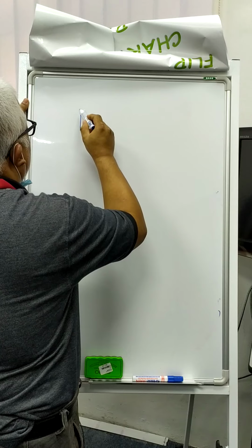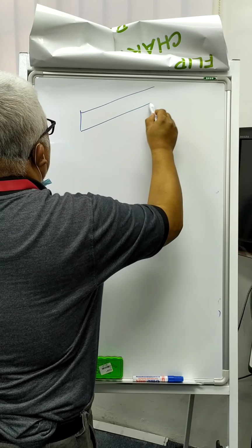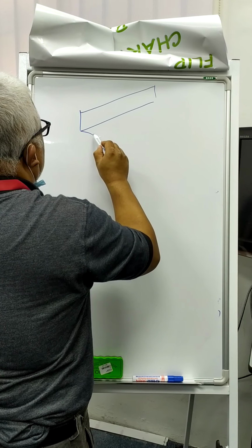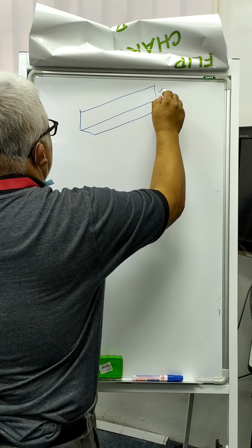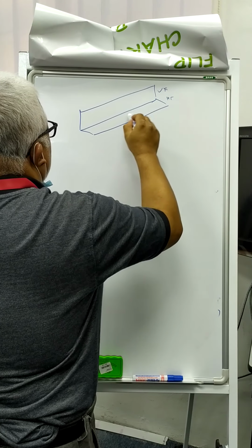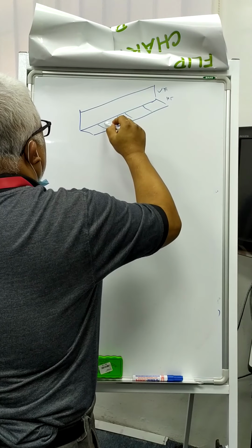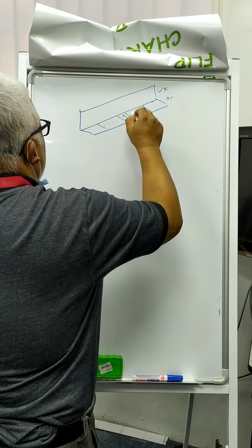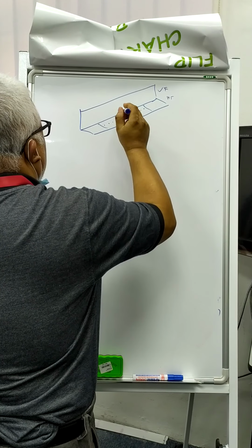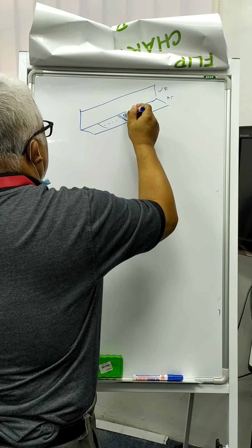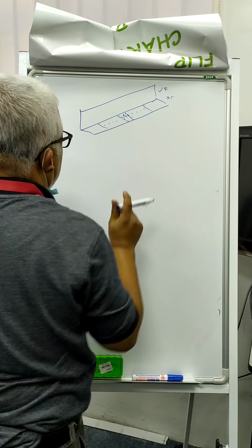We have this angle. This is the horizontal flange, vertical flange, horizontal flange. We have damage. We cut one off. We put a doubler. Install 4 rivets. We may have 2 rivets here, and we install filler behind, so that is hidden behind the doubler.